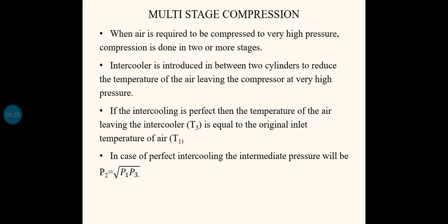If the compression is happening in 2 or 3 stages, then it is called multi-stage. Why we go for multi-stage compression is, as we know, there is a limitation for the compression within a single stage. If the final pressure to be produced by the compressor is very high, then we can't do that compression within a particular cylinder due to the high temperature rise as well as the pressure rise. So there is some limitation for single stage compression. If the outlet pressure required is very high, then usually the compression is done in either 2 stages or multi stages.